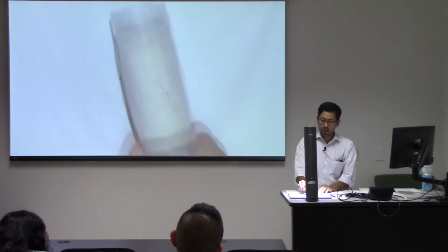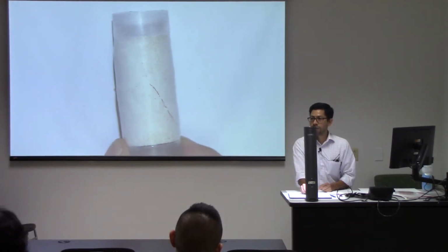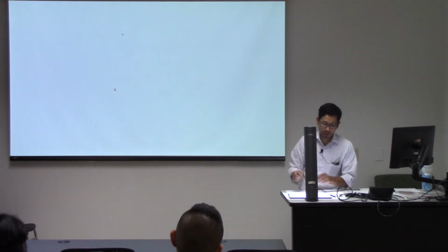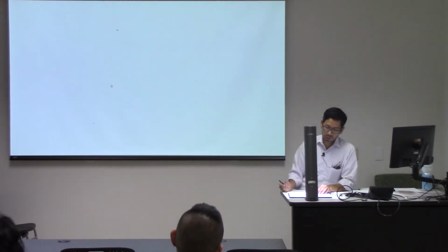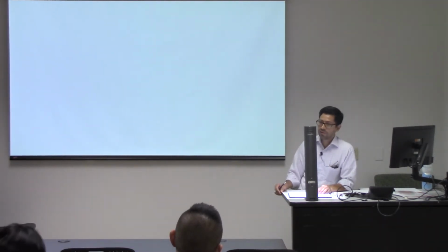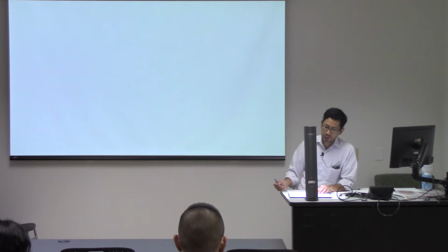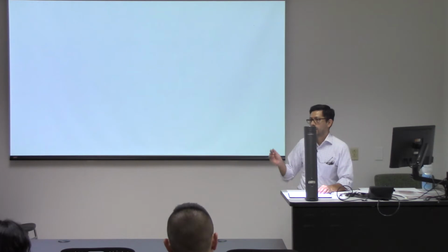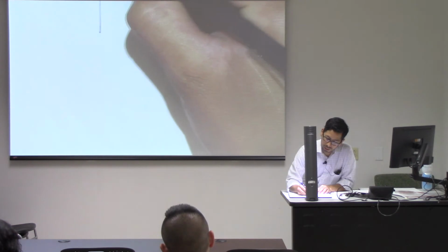This sample was tested in a triaxial machine, and it has a membrane around it, very similar to the ground coffee that we used before. So let me tell you what was going on in this case. We use the triaxial test because we many times want to put fluids inside and test the effect of fluids, or measure permeability under stressed conditions. In order to do that, opposite to what you have done before, but you will also do in the lab, not the coming week but the week after, you're going to get a sample of rock